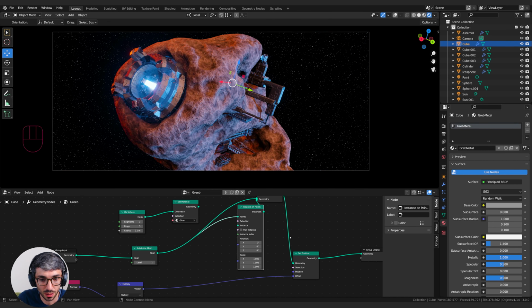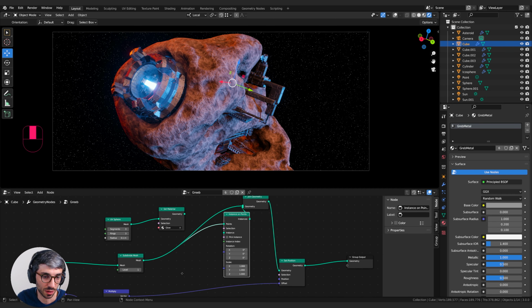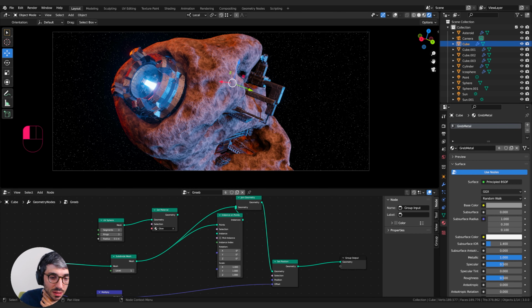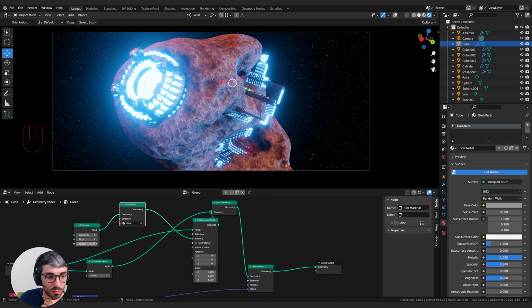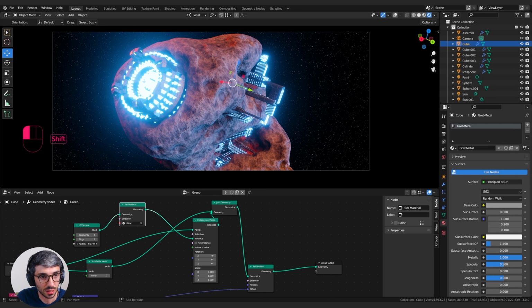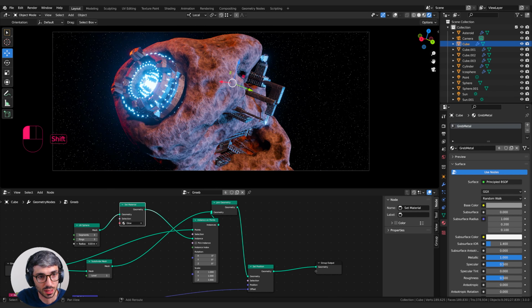In fact, that's way too many, it destroys my machine when I plug that in. It's because we've got so much mesh because we've subdivided it. So we should probably take the base mesh and use it. Let's take the base mesh and plug it in here for points, and see if this does any better when I plug this into instance. Yeah, that's a little bit better. I've also decreased the UV sphere segments to 3, rings to 3, and decreased the radius a lot as well. We just need a tiny little radius.